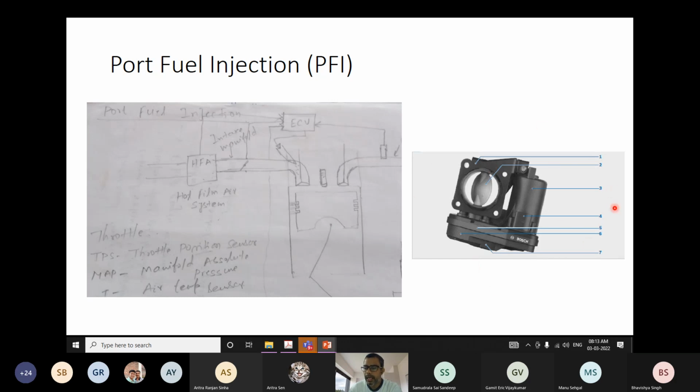your throttle, and then the throttle is opened. Whether it has actually opened or not is the feedback signal, which again goes to the ECU, and the ECU compares these feedback signals to the actuation signals and makes sure that the throttle has opened as commanded. Why does it happen? It happens because the throttle is not opened only based on the acceleration demand. That is also one kind of control system.